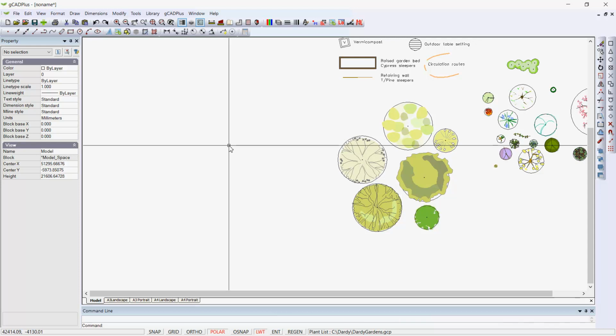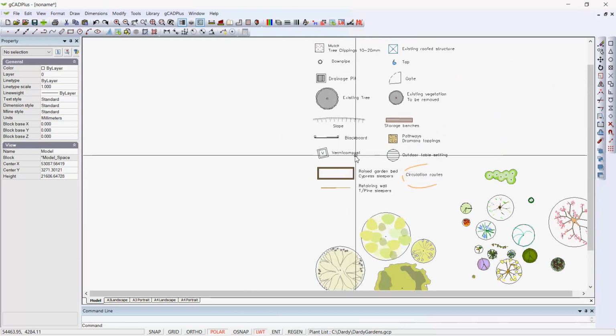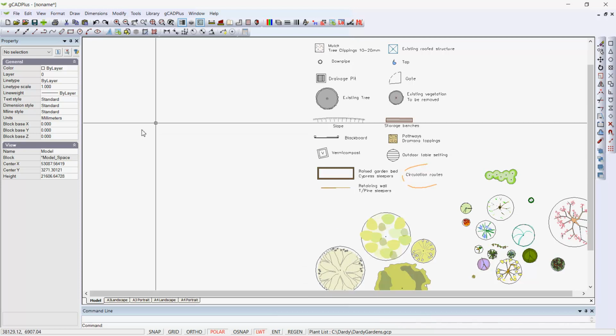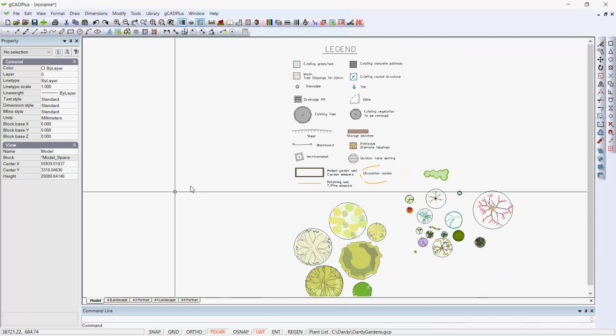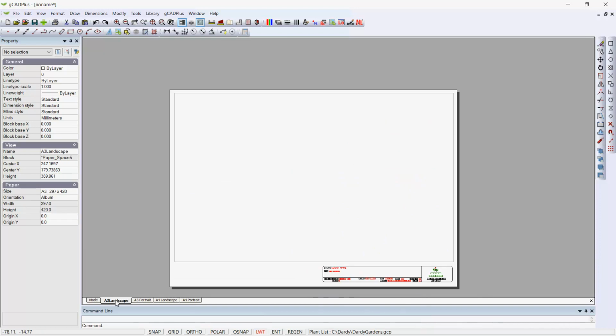So you create one drawing and kick off to the side symbols and other entities that you want to use, put them all to one side, and then work on your drawing on the left-hand side, and whatever you do will appear in that floating viewport.